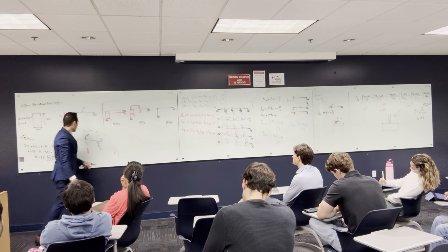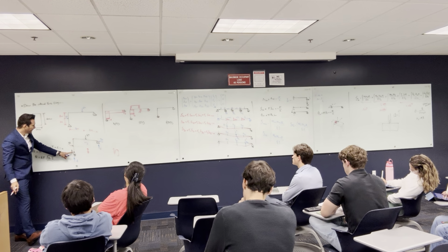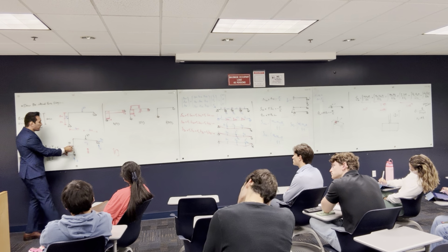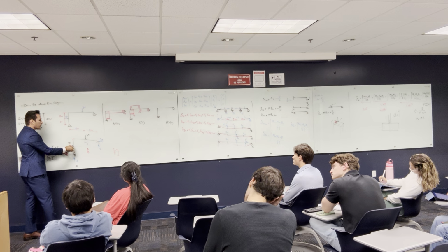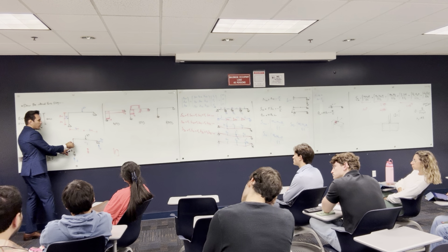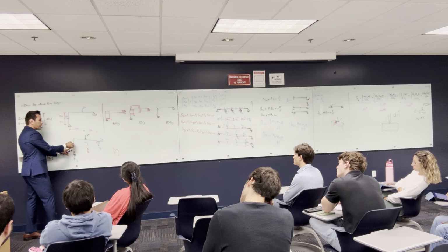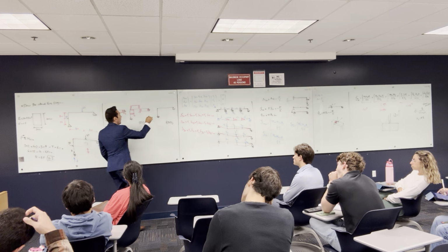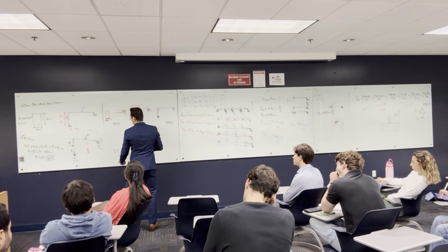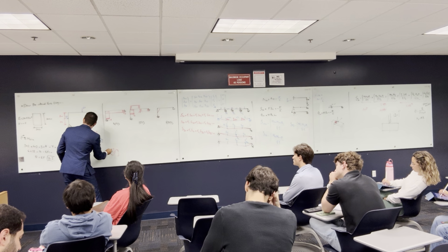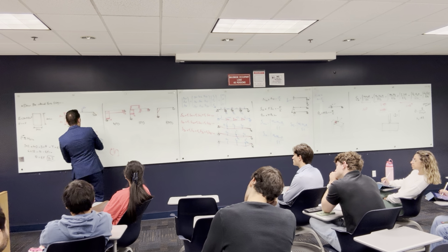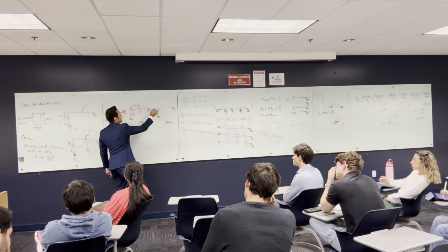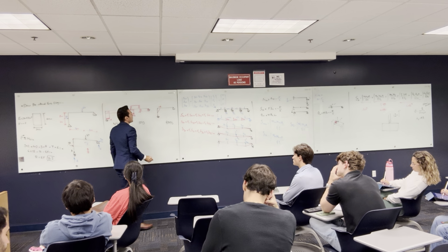All right, bending moment diagram. Here the bending moment is 0 until I come here, and here is where the bending moment is going to start when I go away from the support. So the support is going to be multiplied by 1. So the value of the moment here is going to be 3 multiplied by 2, which is 6. So I'm going to come here, and this is a negative bending moment because the positive is that way. This is making a negative moment in the other direction. So this is going to be -6.